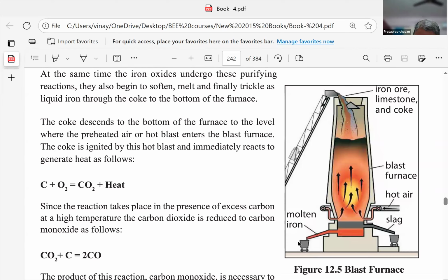It has the mechanism to tilt in this direction, and the flow of the molten metal from the trolley is directed to the mold holes in which the metal is to be poured for different molds. The molds are aligned in one single line, and the molds are mounted on a train or a rail line.